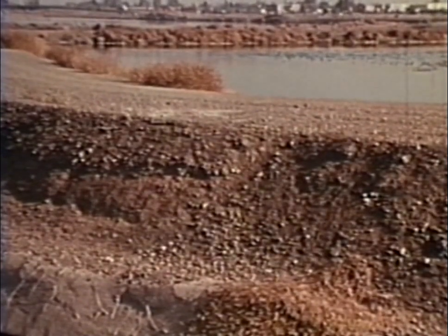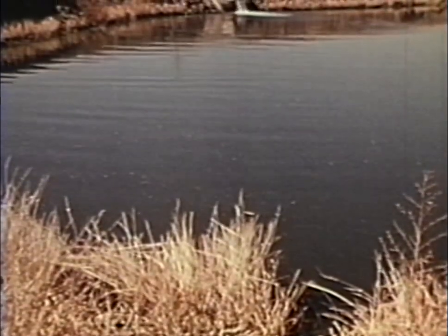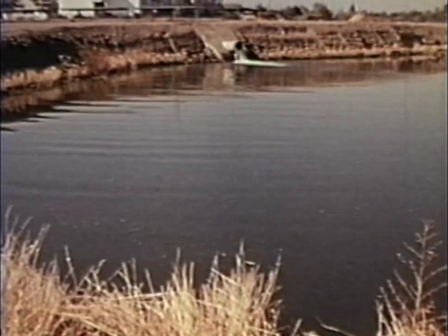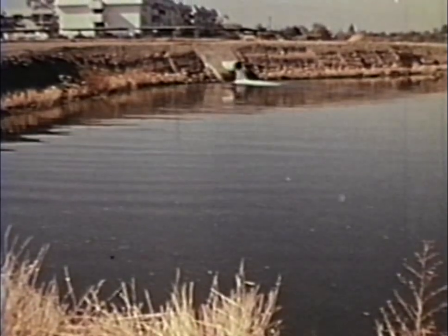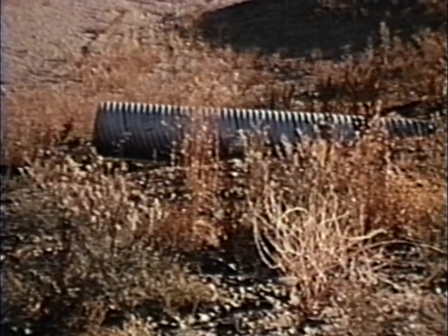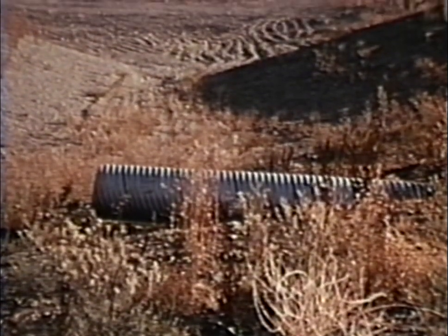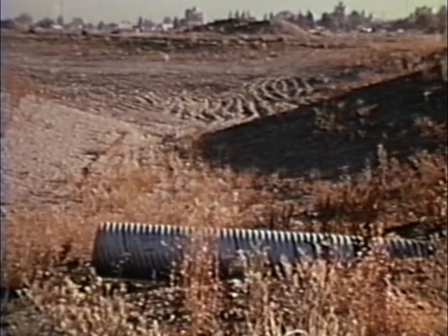From man-made ponds located at many strategic points in this urban area, the imported water seeps downward into the aquifer. They work to get it down quickly with the least loss by evaporation. After use, the pond bottoms are plowed so that sediment clogging will not cause excessive reduction in the infiltration rate.